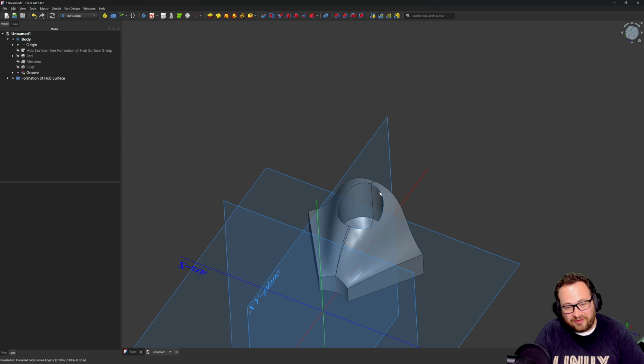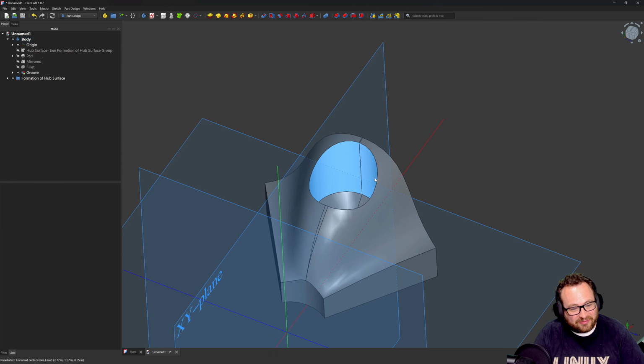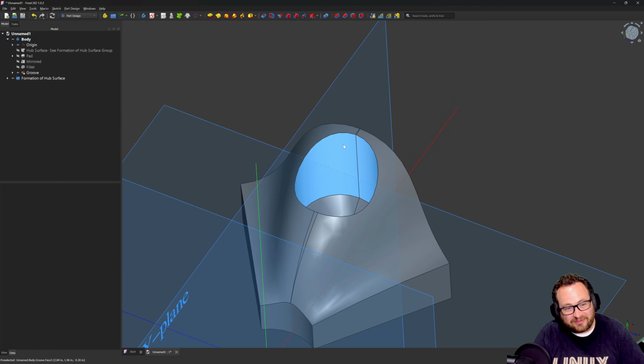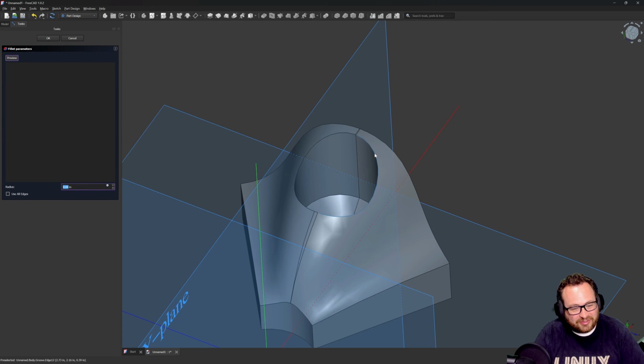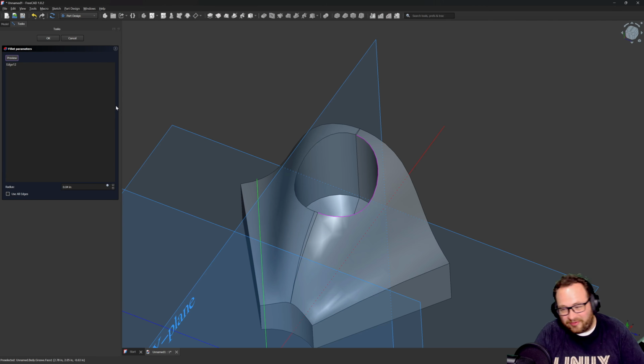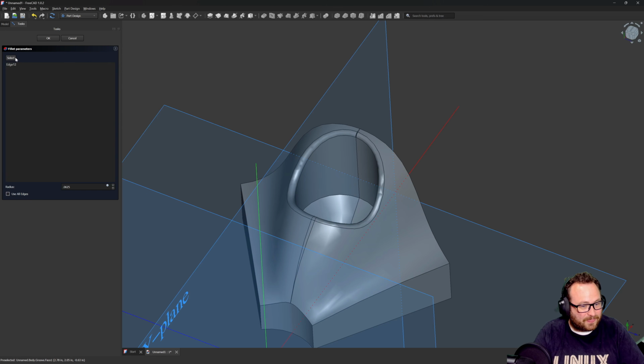I'm going to choose a fillet that I'm going to pattern with using a body, and I think that might simplify things. I don't know for sure if that's the absolute best thing to do, but I think it's a pretty interesting and reasonable strategy. So we're going to add some fillets that are going to be patterned, saving our overall number of manually applied fillets, which may simplify the computation of things down the road as well. Not sure, but that's my running theory. I'm going to say 0.0625 on this radius. If we preview this, we can see that we've smoothed that out quite nicely.